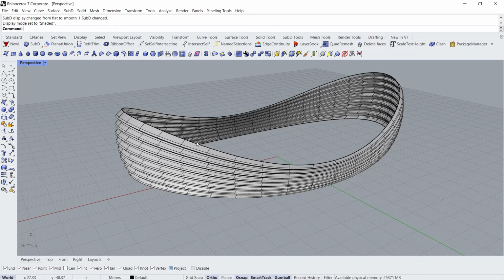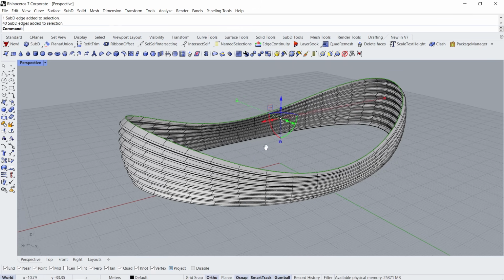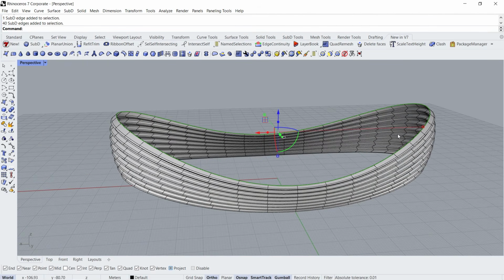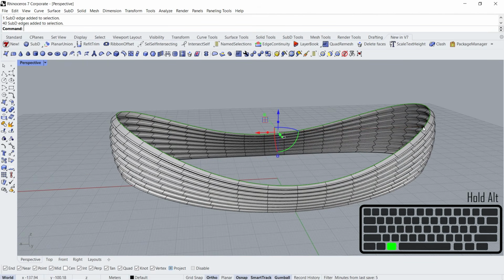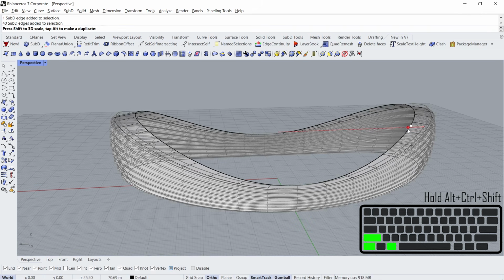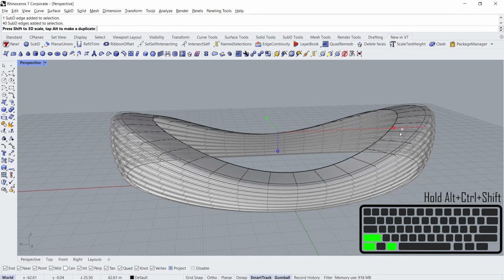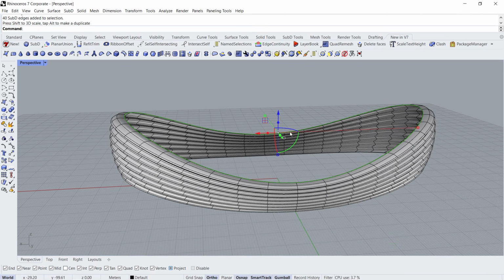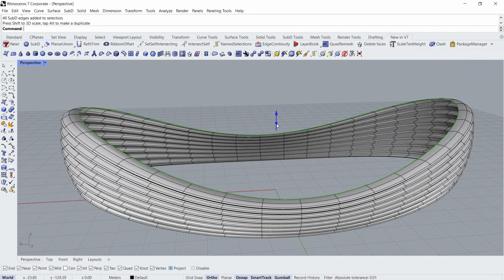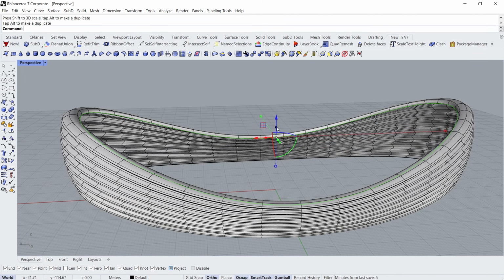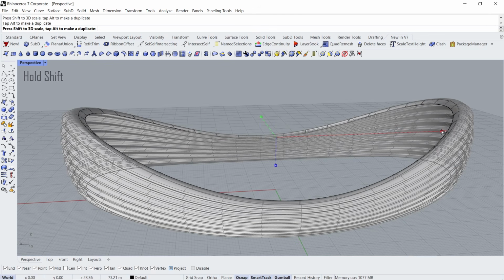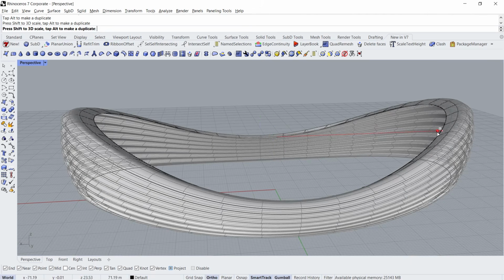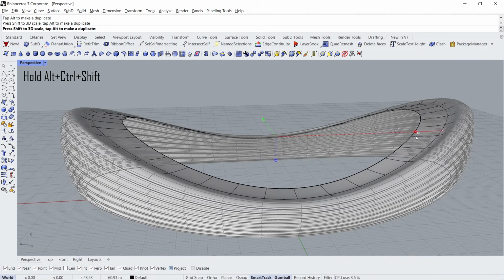Shaded mode. Hold Ctrl-Shift and double-click to select edge loop. We must extrude this boundary inward proportionally. Hold Alt, Scale. Hold down Shift and Ctrl without releasing the Alt. Extrude in the Z direction. Hold Shift to scale proportionally. Hold Alt, Scale. Hold down Shift and Ctrl without releasing the Alt.